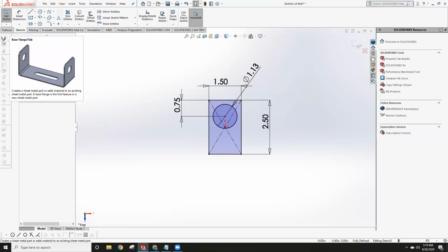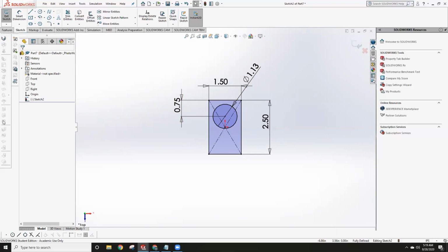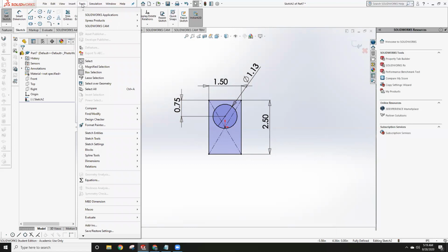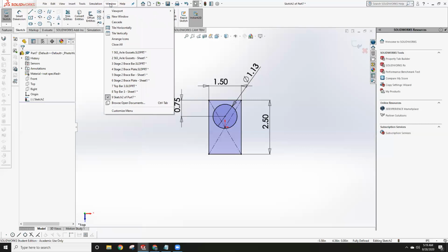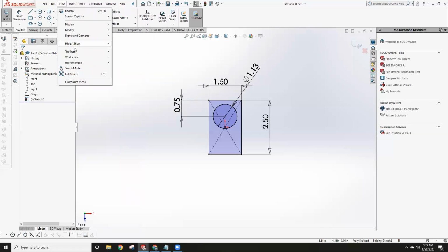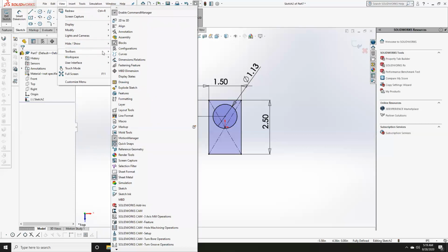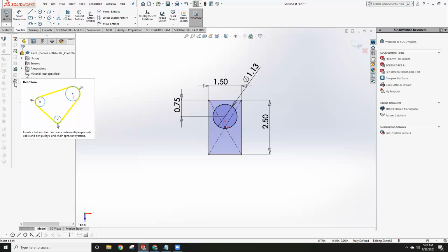And then right here, I have the sheet metal toolbar on the side because I work with sheet metal a lot, but chances are you do not have it already on your toolbar. So what you'll be doing is going over to, I believe it's the Tools tab, actually maybe it's in Window, View? Toolbars, yes. So you're going to go to View, then Toolbars, and I have sheet metal selected. I don't have the rest of these selected. I have these two, I don't know why. And I have blocks. I use sketch blocks a lot, they're very handy. But yeah, this is just really simple.